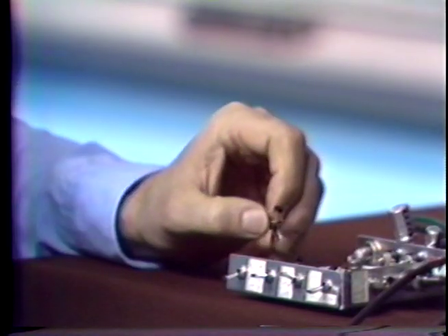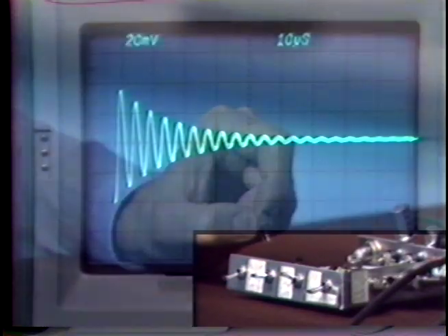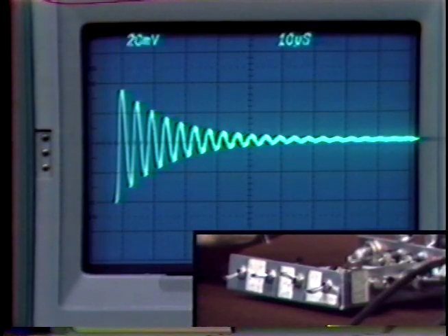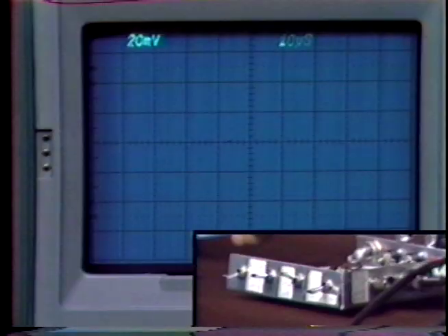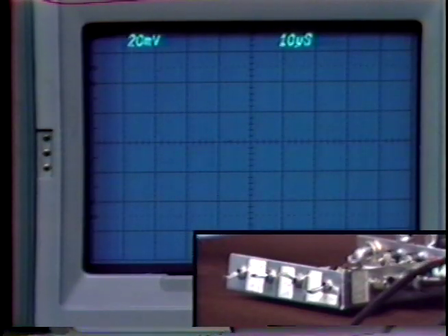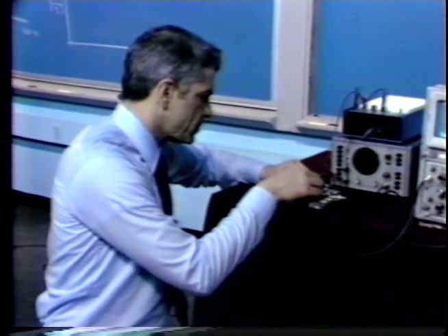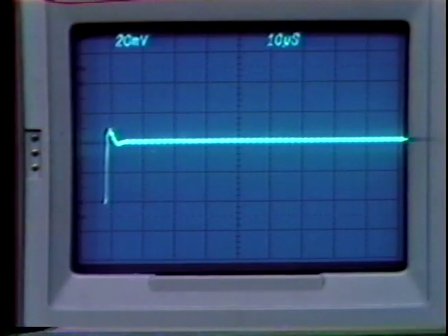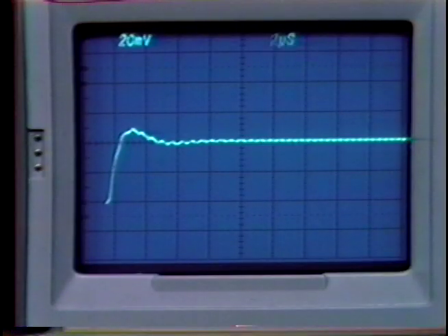And what I'd like to do is look back at the oscilloscope trace and recall that the settling time with 1/s compensation is in excess of 100 microseconds. And now let's go to the compensation that includes a zero. I'll remove the single capacitor that was doing the compensation before, and I'll put in the series RC connection. And when we do that, we notice a very dramatic improvement in performance. We're now able to go to a much faster time scale.